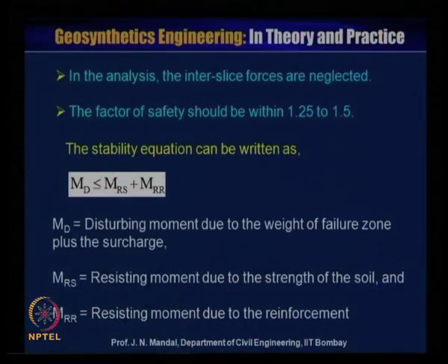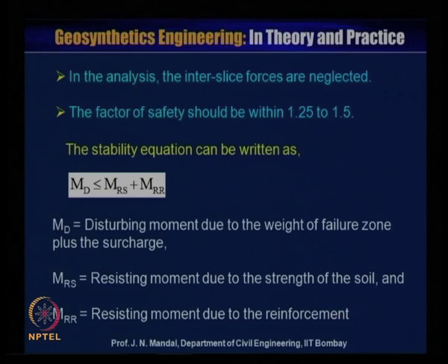Now, in the analysis the interslice forces are neglected. The factor of safety should be within 1.25 to 1.5.